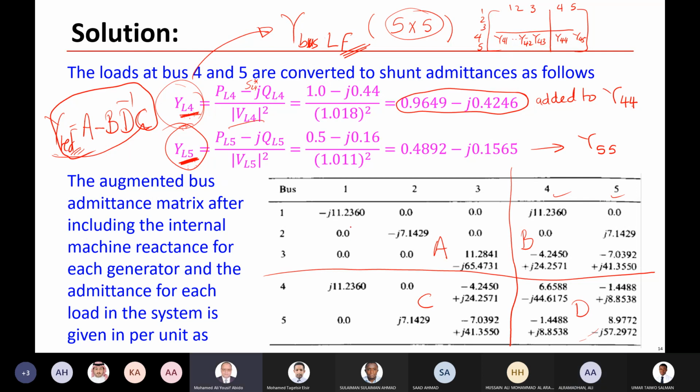Of course, the Kron reduction can be done column and row wise, or bus wise. And I don't know whether you still remember in 520, for example, if you want to eliminate bus number 5, and then we eliminate bus number 4 later on, sequentially, we can do this. This is Y11. This is Y11 minus, you go forward here.